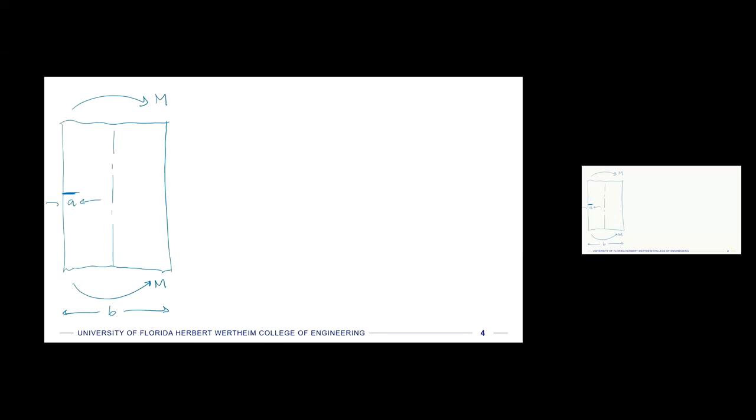So we know that the stress at that point, right, that is a critical point. If we go back and think about all of our other types of failure modes, right? So the stress due to bending there, right, we can write it as something like this, 6M divided by t times b squared.